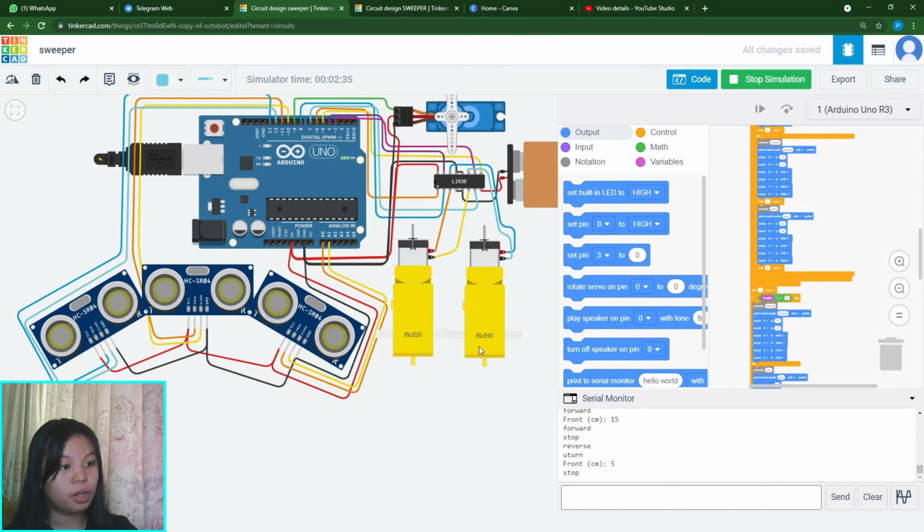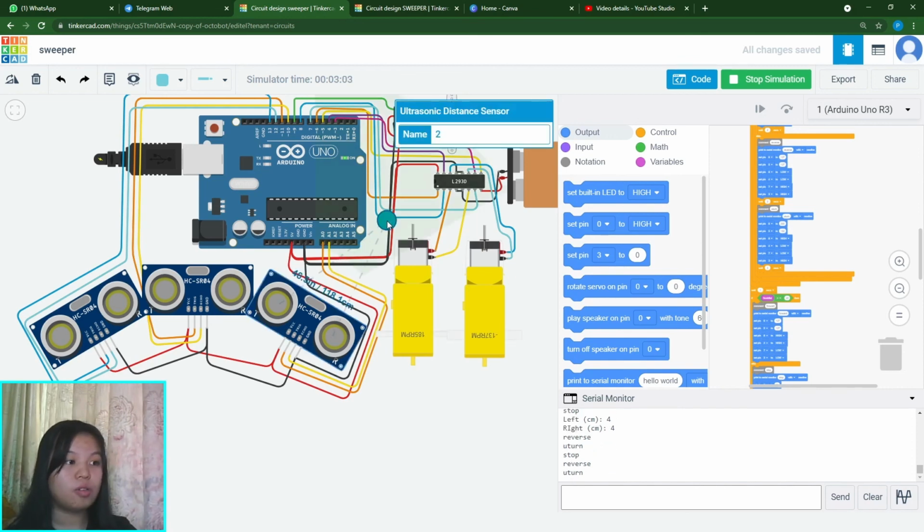We see it stop after detecting the front, then it reverses at negative 114 plus RPM, and then it makes a U-turn. So we see positive 184 and negative 136. This is the part where it U-turns. One is moving positive, the other is moving in reverse, which is negative, one at a greater speed and the other at a lower speed. This is the part where we make the U-turn. Okay, so these are all 5 scenarios, and it shows that everything works well.